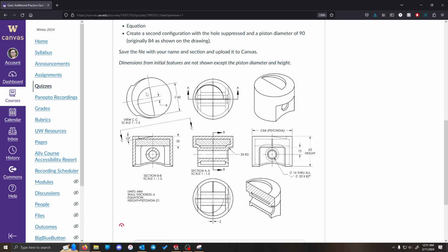One other thing I want to bring up about this cut is that it is a little ambiguous as to whether or not you would want to do this as a cut extrude using some reference plane or a cut revolve, which we could just do on the top face. In this case, we would know that it has to be an extrude because if there's a revolve, we would actually see two sort of arcs on the inside, one from where it starts on the top surface and then another one from where it ends on that flat surface on the inside.